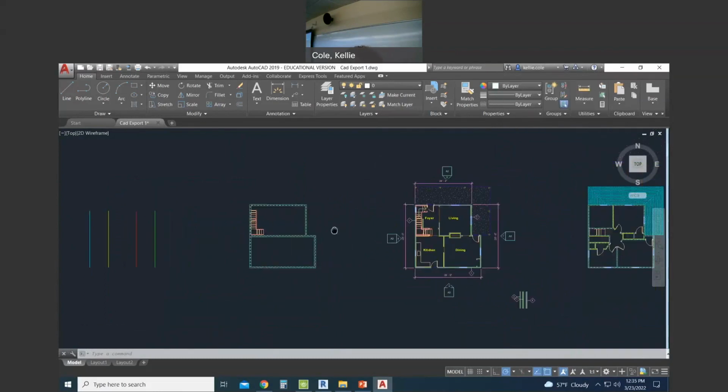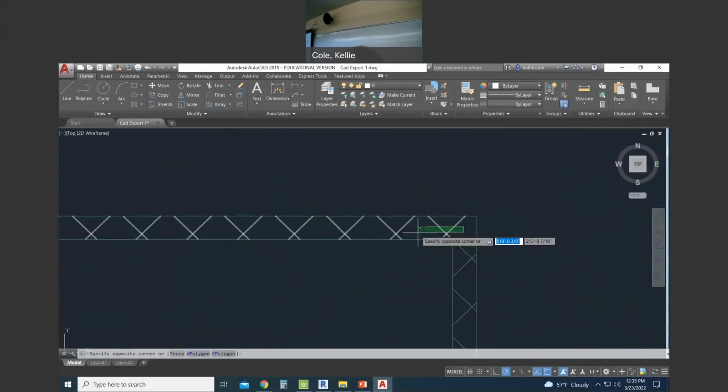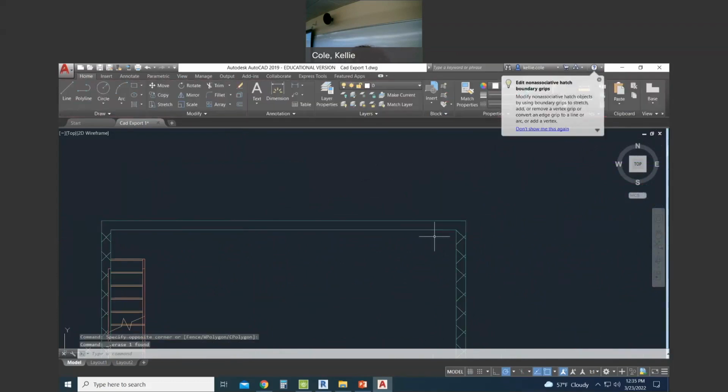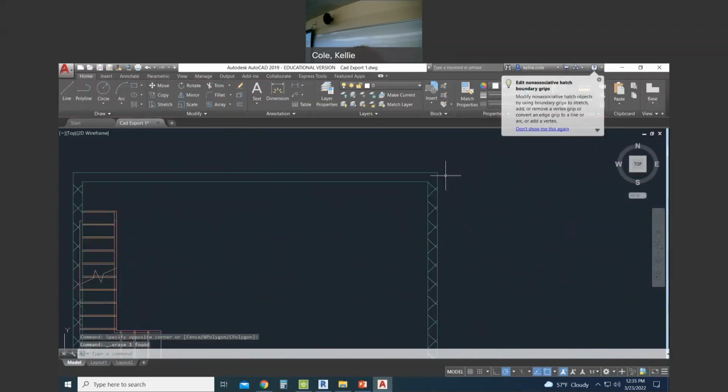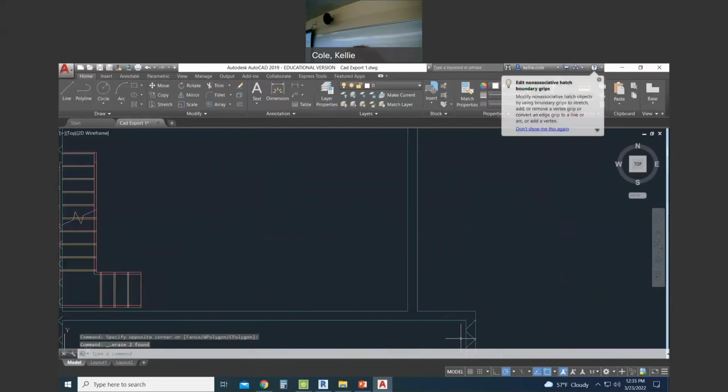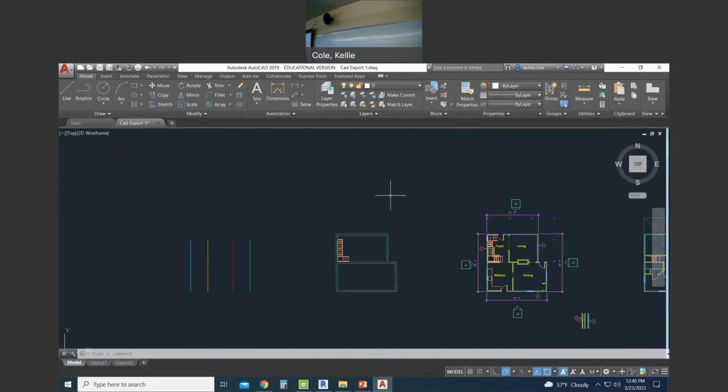So the first thing we're going to do is I want you just to delete the hatch. I don't need to know that this is, and if I delete some things, that means I don't have to change all the layers. So I'm just going to select the hatch in my walls, left click once and just tap it and delete. Yes. So red outline, yellow, everything else, right? And then when it laser cuts, pops out my floor plan. But it doesn't pop out all the walls and all the beds because I just scored it, okay?